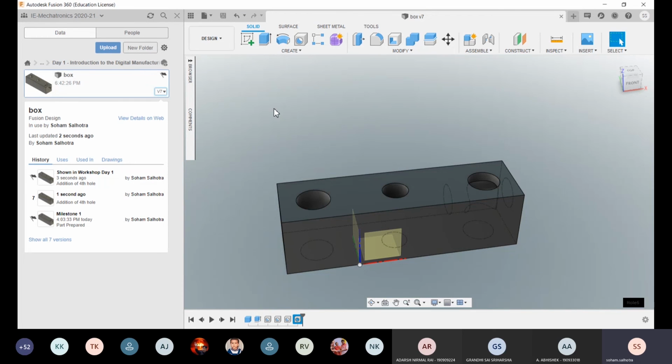The advantage is that when you import designs in Fusion, if I wanted to go to that particular shaft and make it longer or shorter, or maybe add some grooves or threading in it, I can do that independently. The changes in that file will reflect here automatically because that part is imported here. That will go in the users tab.